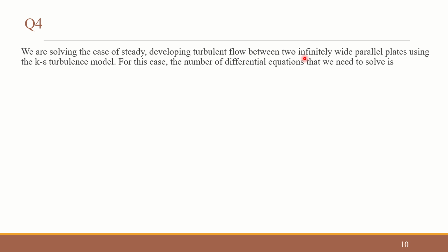So we will have to solve two momentum conservation equations and one partial differential, continuity equation. So we will have three equations. Now, instead of laminar flow or the regular flow which we observe in our cases, we are going one step ahead and we have to solve for turbulent flows. And what method are we using? We are using the K epsilon turbulence model.